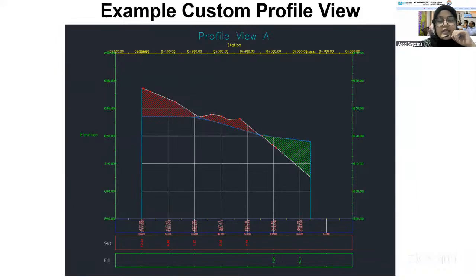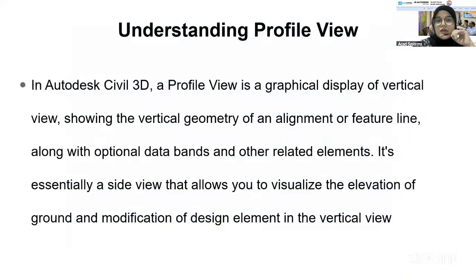Here is an example of the custom profile view that I'm going to show you today. By the end of the lesson, you will get more or less this kind of custom profile view. As you can see here, we're going to create the band data like this, and then we change the color, we change the size of the text, we add the hatching, we change the view style, and so on. Right? So before we go to the lesson, I'm just going to slightly introduce what the profile view is, for you to have a better understanding.